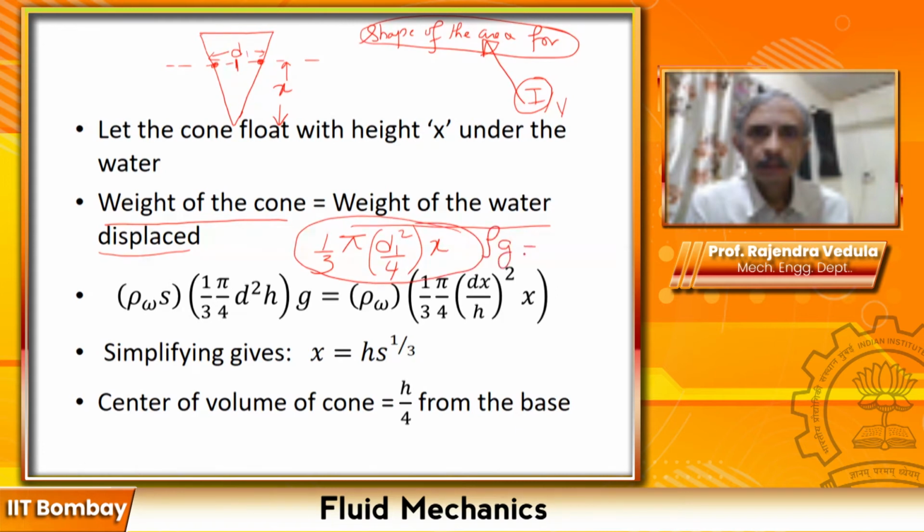This is the buoyancy force. Everybody agree? The buoyancy force is the weight of the volume of the submerged body, 1/3 area of the base into the height, multiplied by rho g.